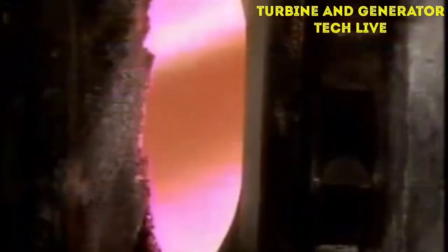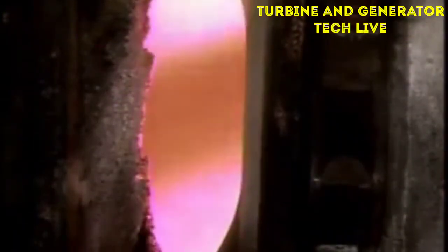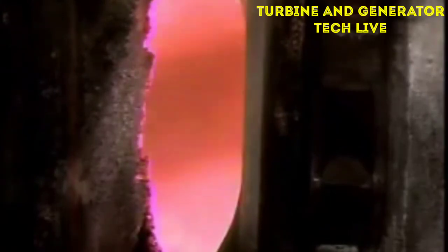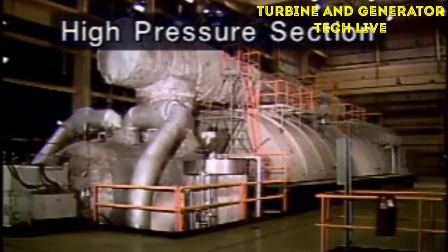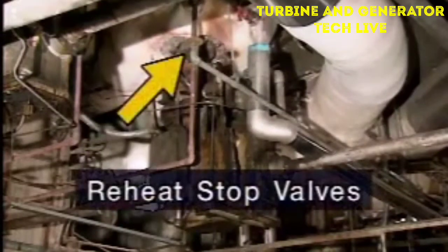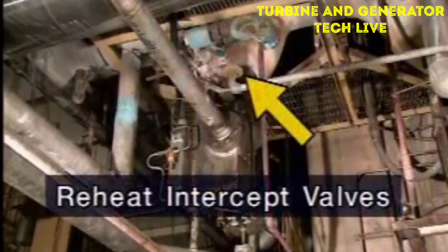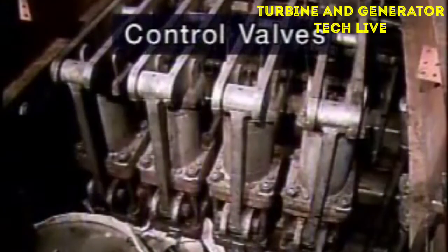For this reason, it's often necessary to return steam to the boiler for reheating before it passes through the entire turbine. This reheating most often occurs between the high-pressure section and the intermediate pressure section. Reheated steam is returned to the turbine through reheat stop valves and intercept valves. These valves, along with the stop valves and the control valves, also provide protection for the turbine.